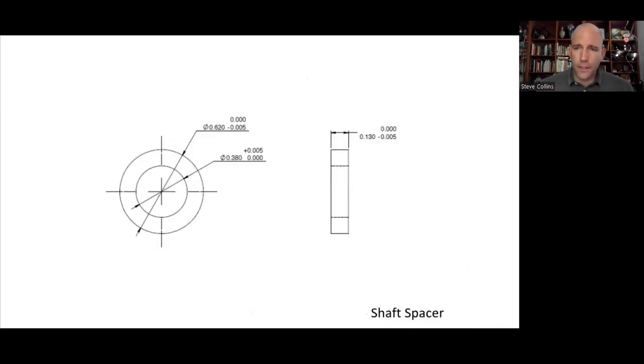All right, how about this component? Take a look, think about it, make a guess, and then come back. And you can hit pause now. If you got a guess, this would probably be a good choice for plastic. Likely, since it's a spacer, it probably won't experience a lot of loading. It's just there to keep things well aligned, especially when you're putting the system together. So, some kind of plastic, maybe a PEEK. You could probably potentially order a component that has the right size as well.